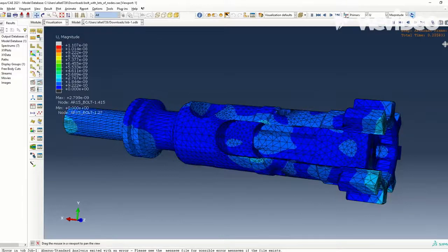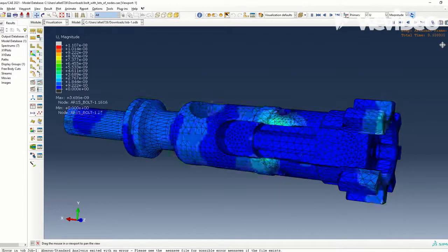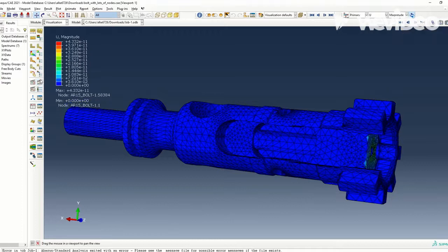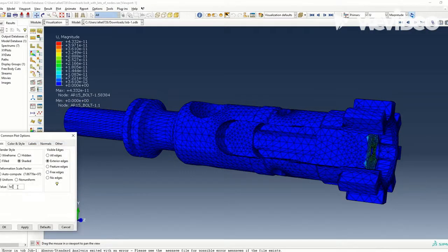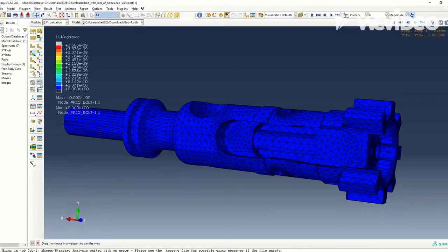Some of this violent deformation is due to the pressure curve data. The pressure curve is not complete through zero pressure. Using the data provided, the bolt's face goes from experiencing 20,000 psi to 0 almost instantly. Although this is not completely the experience of the physical part in a real firearm, the pressure does drop off very quickly after the bullet has left the barrel, making this simulation not completely unrealistic.